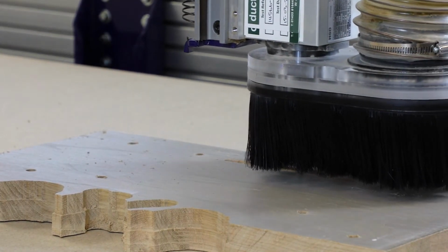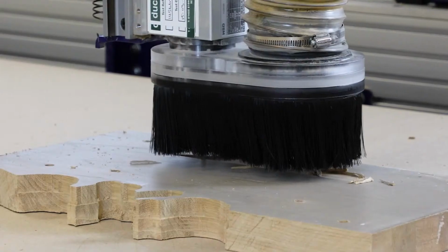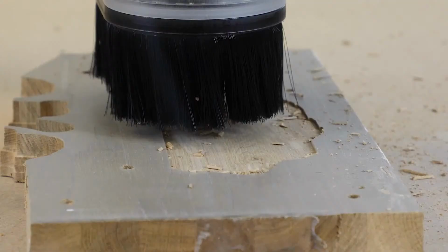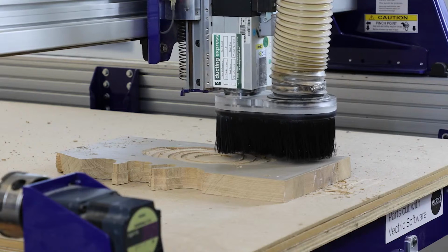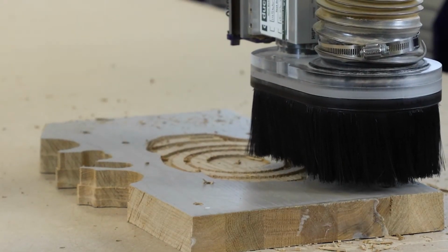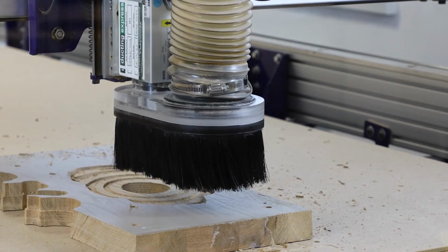So what I did was I gave it a base height of 1.1 inches. So it's a zero plane that's been merged in with a base height of 1.1. And that stops the tool, again, from going down too deep. Really quite effective, and also it saves a bit of time as well if you position it properly. And this roughing pass is almost done, and it's exactly what I expected it to look like.